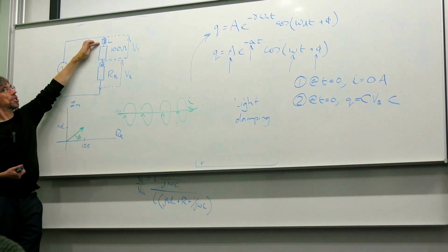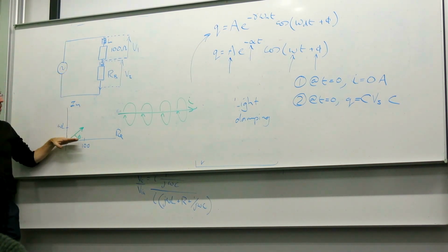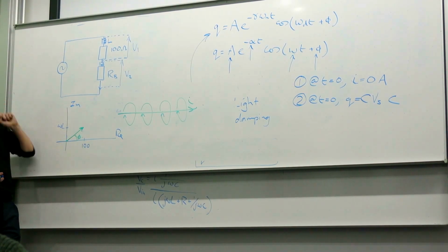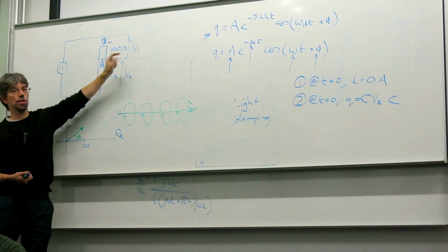However, if the parasitic inductance is different between those two, one will be rotated relative to the current by a different amount than the other. And I think some people saw that at high frequencies, where the inductive part does actually become a bit more significant. They might see a phase shift between V2 and V1.